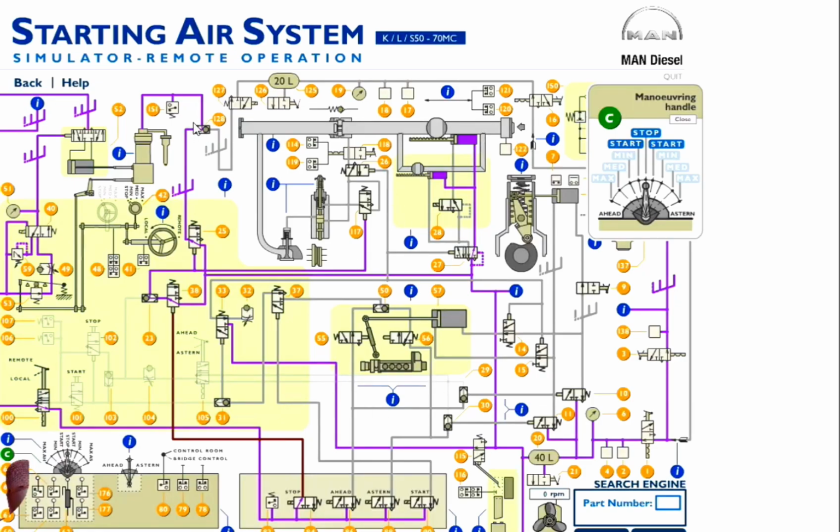I had an experience. I faced that one of the starting air distributor valves was closed by vibration. That was an old type valve, a simple ball valve without any lock mechanism, and that valve was closed and the engine cannot start, okay. While I was an apprentice engineer on that ship, I opened this kind of diagram, and I was looking at how the line is going and where it's connected and from where it started, to locate the problem, okay.